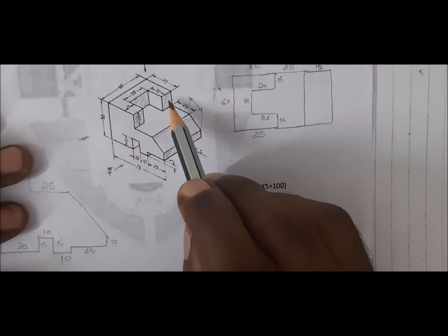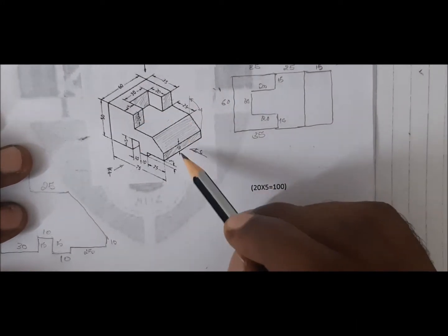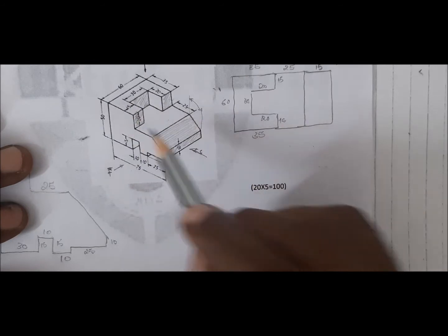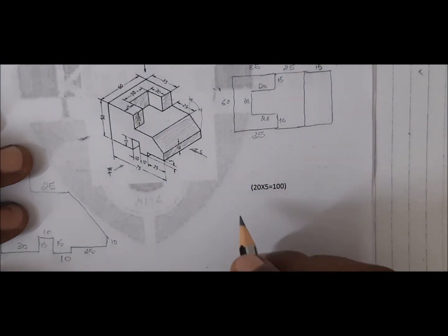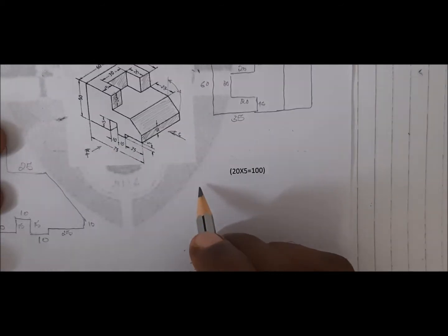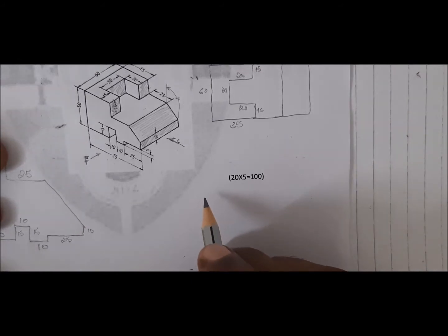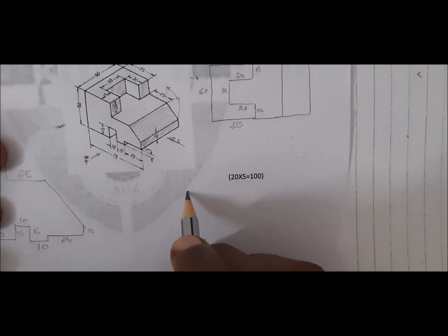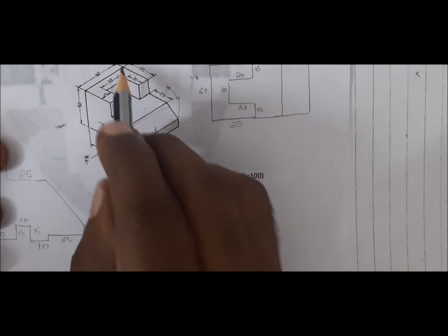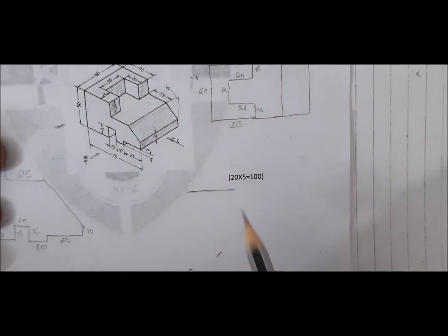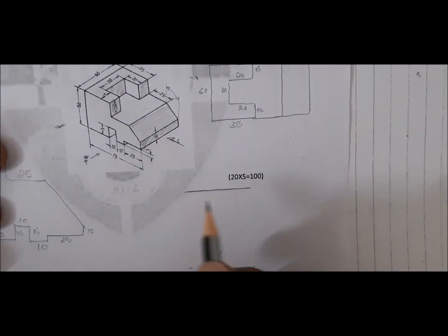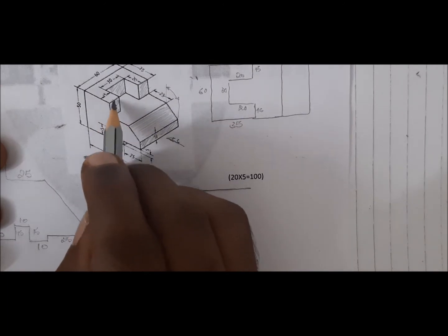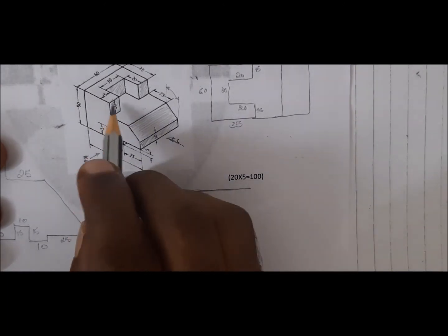So all the vertical surfaces are like that. So you'll see this rectangle, this rectangle, this one, and this one. You won't see these rectangles. Okay, so when you draw the figure, I guess you can see this. I'm going to make it very small. The whole of 60 mm from here to here. I'm going to draw that line. And inside that 60 mm outline, this rectangle, 20, 15.